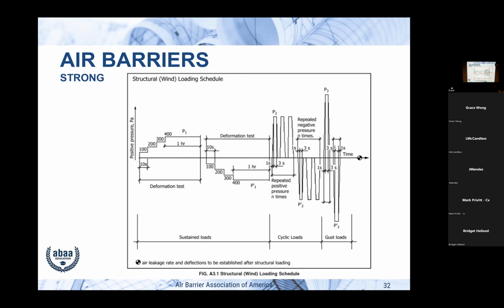What if the building's more than 3 stories? Why should we care? A 3-story building, let's say that's 40 feet high, just for rough figures. What if we go to a 10-story building or a 20-story building? Why is that important if we're talking about air barrier assemblies? Yeah, the same wind, same day, same location, completely different pressure difference.